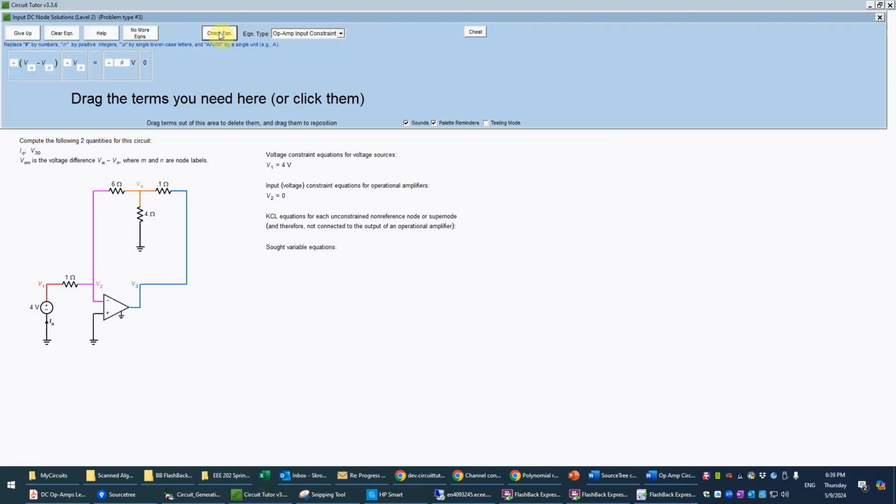And that is correct. Then we need to go to the central equations in any nodal analysis, which are KCL, or Kirchhoff's current law equations, summing the currents leaving or perhaps entering each node. So we have 4 nodes to consider here, V1, V2, V3, and V4.